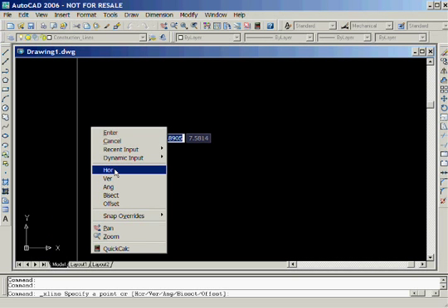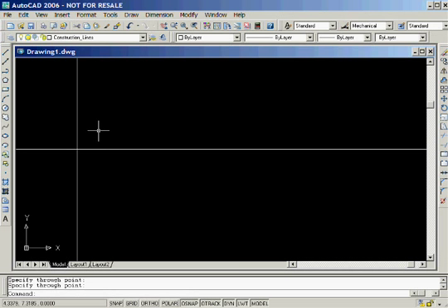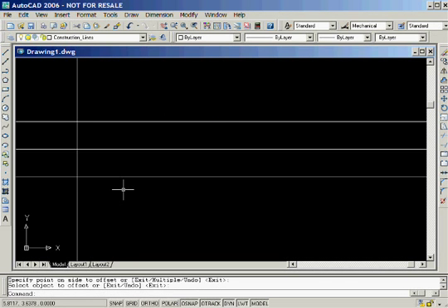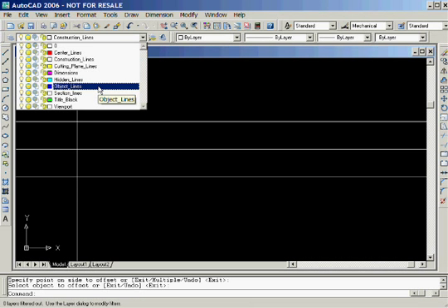We'll now draw a vertical and then a horizontal construction line that will serve as references for the circular features of the top view. And then we'll click on the offset icon and add two more horizontal construction lines that are 1.75 units from the first line.